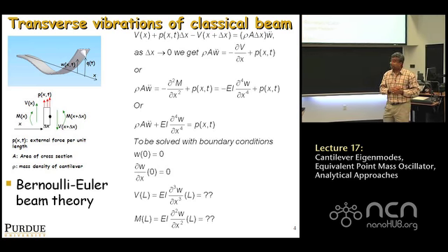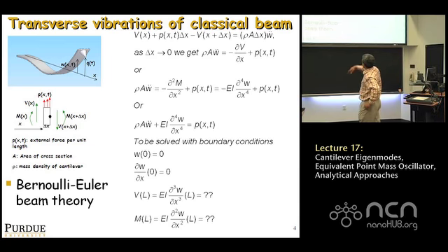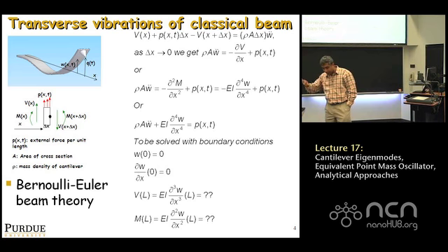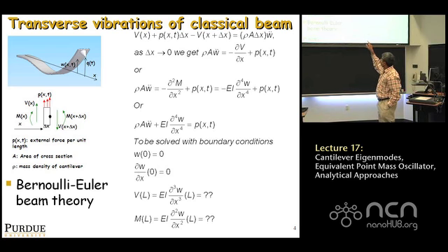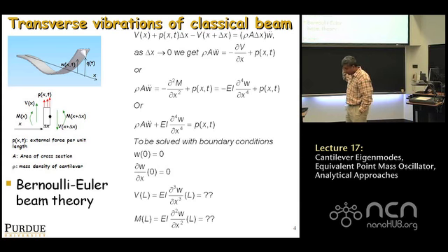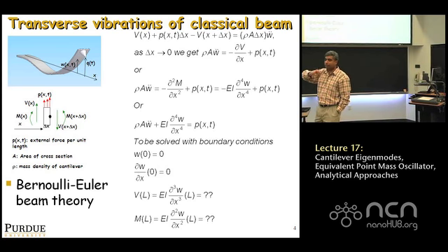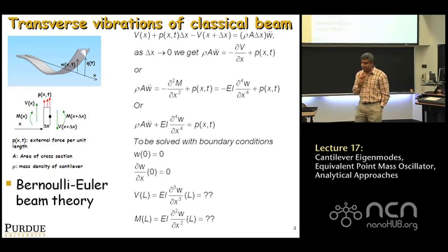So you need to include an inertia term. How do we include the inertia term? Well, on the top left, you see a sketch of a beam. It's a snapshot as it's oscillating, so that the centerline deflection W is a function of spatial coordinate x and time both now, all right? Q corresponds to the motion at the tip, the up and down motion at the tip specifically, okay?